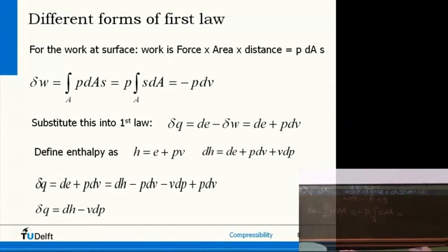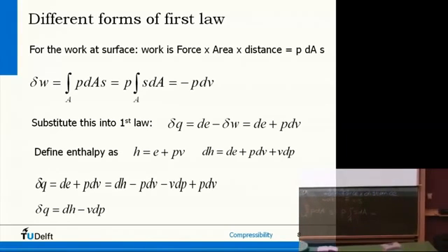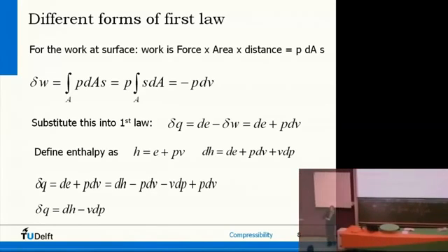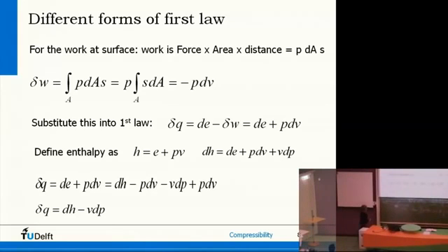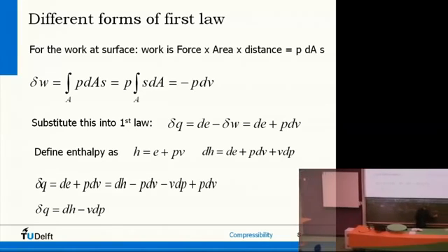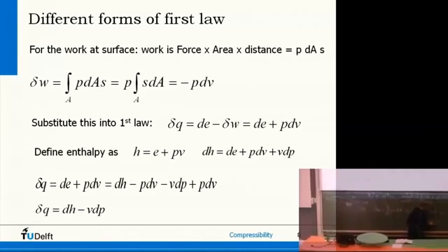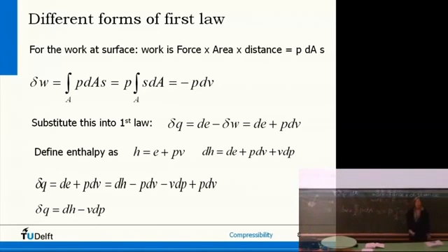So we're integrating now S, so that's this distance, times area. So that's actually the volume, right? The volume displaced by the pressure. So this is distance times area, so volume. And what is it? It's the change in volume due to this force. And it's per unit mass, so it's a change in specific volume, right?